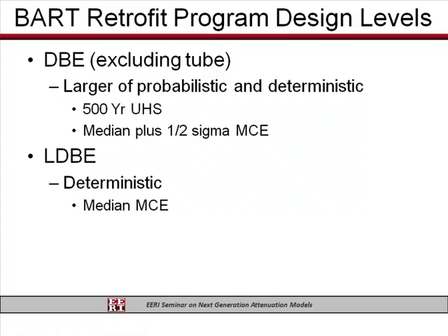In the 2002 study, they also developed vertical ground motions based on empirical V over H ratios applied to the horizontal motions. For this updated study that Norm and I performed, we didn't actually do any vertical motion analysis, partly because the vertical NGA models are still in development stage, and so it wasn't as simple to update the ground motions using the V over H ratios. And then in addition, what they also did in the 2002 study was they came up with general directivity factors and also a fault normal and fault parallel component factor, which again we didn't analyze in this updated study.